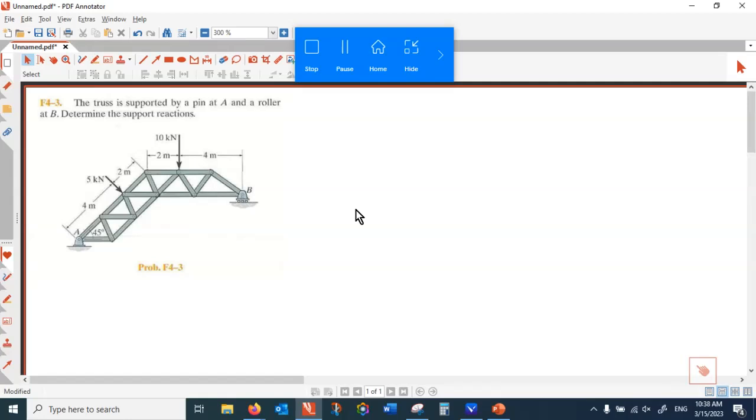You only have to be mindful of the critical one. Whatever is not critical can still take some load, but you keep an eye on what is critical. That's the bottleneck, so that is the main objective of studying the truss structure. We offer different techniques to study that. But for now, as a prerequisite to finding individual forces, in most cases you need to find the reaction forces in the supports.